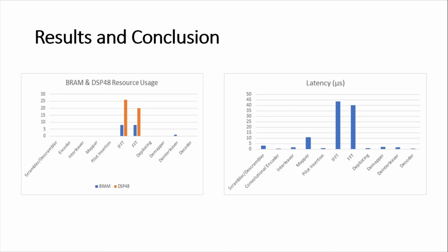Performance of the implementation is measured using the data processing latency of the final design. The transmitting and receiving devices record 16.17 and 15.7 milliseconds respectively for exchanging 512 bytes of data. With the success of this implementation, this can be further extended into a product with both commercial and academic usage.